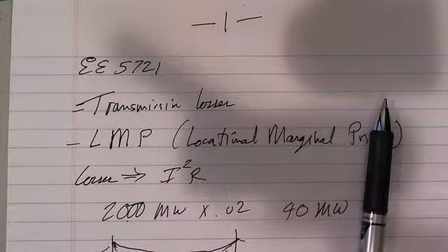The other thing that's bad about these, not paying attention to the losses, is that as you heat it up and let it sag lower and lower, the metallic goes through a process, and when it starts to cool again, when you take the load off of it, it doesn't go quite back to the original shape. It's now got a permanent little sag to it. You can't do that too many times, and you have to restring the lines. So you don't want to overload the lines, and the transmission losses can be destructive.